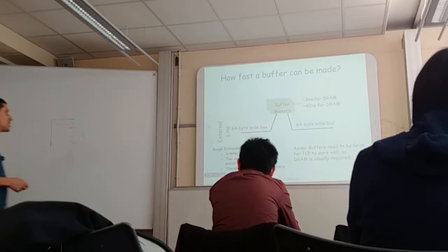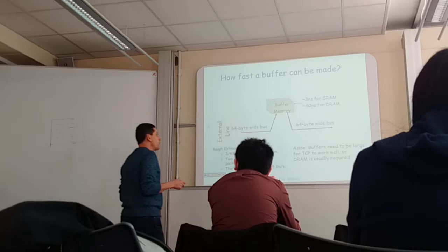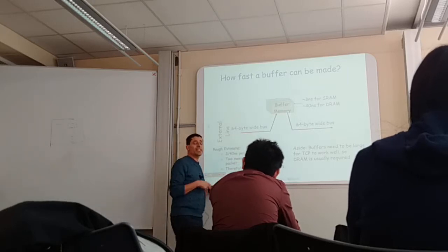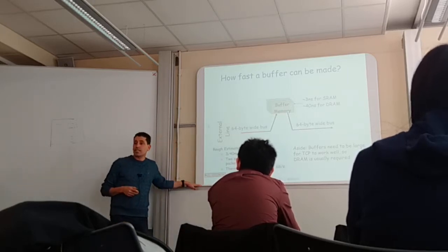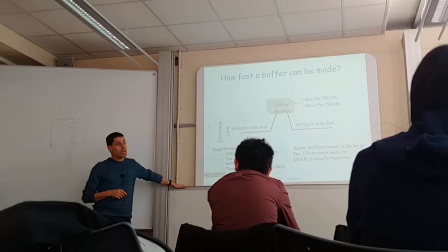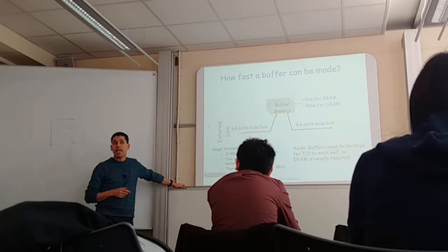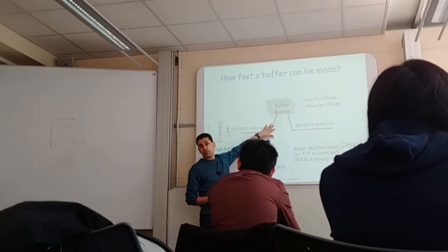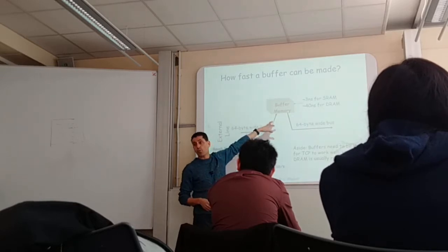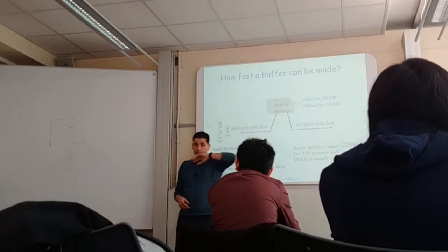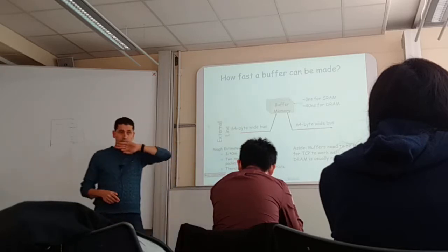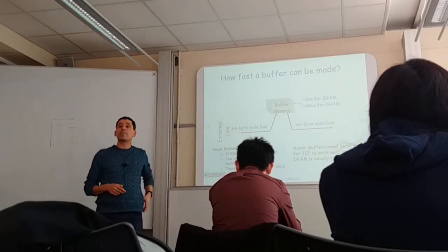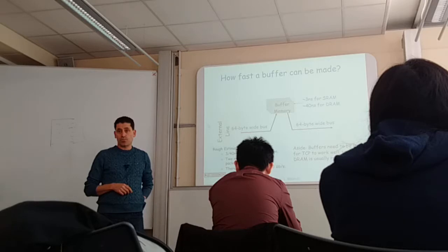Now we wanted to see how fast can I write packets, or what is the maximum bandwidth I can achieve with these memory specifications. So if I have an SRAM that has an average access speed of 3 nanoseconds, and I'm having packets that come in 64 bytes, in one shot you can write 64 bytes in that memory. How fast can I have my memory? What is the speed they can have? What is the bandwidth that they can achieve with my router?